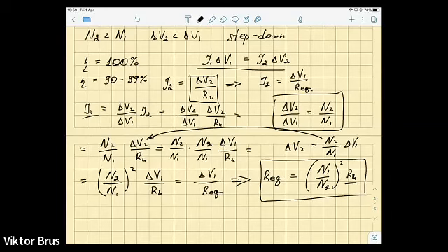Also, what is very important, that power is dissipated in AC circuits only over active resistor. However, in the case of capacitor and inductor, we only twice per period accumulate energy in form of electric and magnetic field, and then twice per period return this energy back to electric circuit. There is no dissipation of energy over these circuit elements.